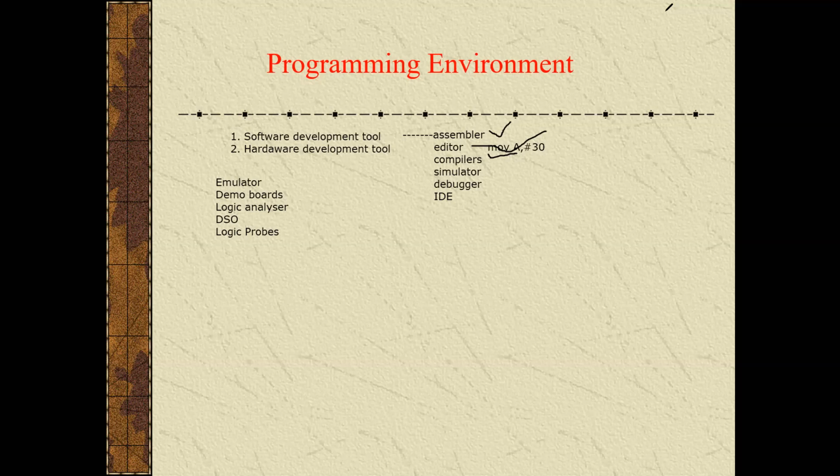As each instruction in the assembly language program is executed, the emulator takes a snapshot of the register contents, the activities on the address and data buses, and the state of the flag register. The emulator stores this data as trace data, and it is possible to take a printout of the trace data so as to analyze the results produced by the program on a step-by-step basis.